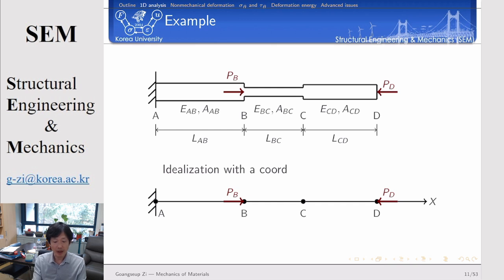We are talking about how we use this navigation map. We start from the displacement field, the definition of the displacement field, and then we calculate the corresponding strain. And then, next step, we calculate the stress, and then we check the force equilibrium. That is the procedure of analysis for any kind of structural or solid mechanics system.